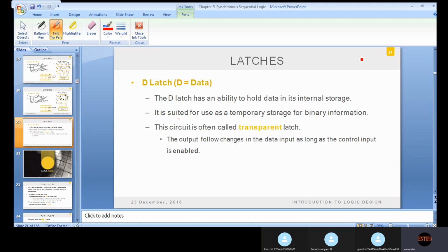Okay, so let us suppose this is your chip. There is an error at this point. How are you getting a fault here? How will you test this fault? To analyze this fault, you need to give some inputs. Here you have the output pin of the chip. To give inputs up to here, you need to have a series of scan chains.